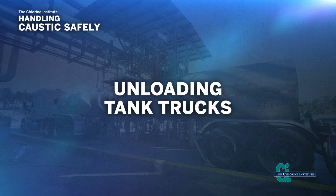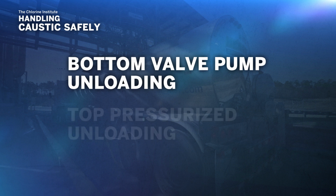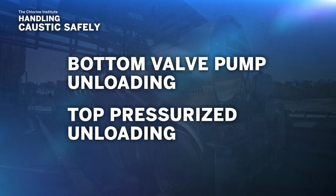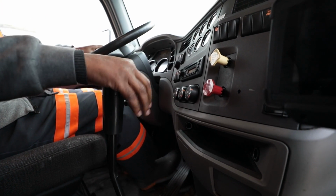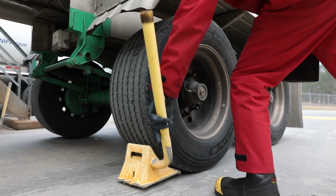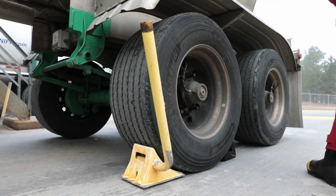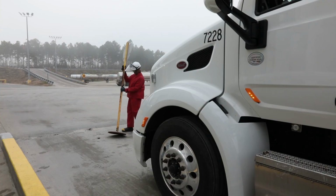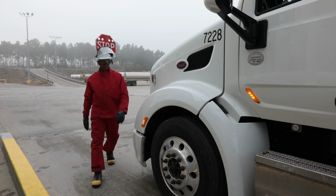There are two methods primarily used for unloading tank trucks: pumping caustic from the bottom valve to the storage tank, and pressurizing the tank truck with compressed air to push the caustic to the storage tank. The truck's parking brakes must be set and the chocks should be installed. Ensure the truck driver complies with company procedures, including the use of pre- and post-unloading checklists.